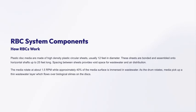As the media rotate at approximately 1.5 revolutions per minute, about 40% of their surface area is immersed in wastewater at any given time. This rotation is crucial because it ensures that the media gradually come into contact with the wastewater and the biological slimes on the discs. When the discs turn, they pick up a thin layer of wastewater, which then flows over the biological slimes.